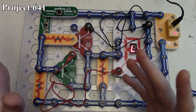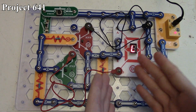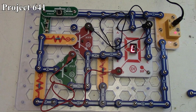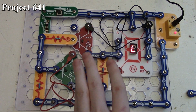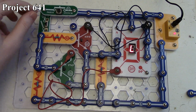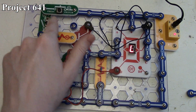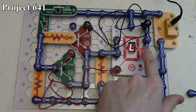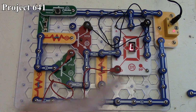Depending on whether those are turned on or true, as we call it, we'll determine whether the output condition is true or false, or in this case, low or high, because it's displaying an L. Our PNP and NPN transistors are handling the logic portion depending on the conditions here. So when we have our switches in the off position, we have two false statements, and the 7-segment LED shows a false statement, saying that it's low.